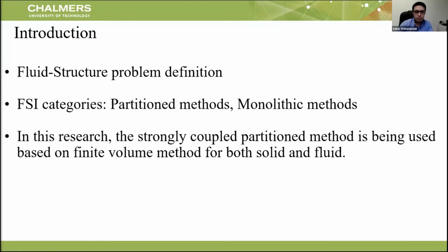In partition methods, the solid and fluid domains are solved separately by using one's favorite numerical method and possibly non-matching computational grids. Partition methods can be divided into strongly coupled schemes, which enforce the discrete counterpart of both coupling conditions up to a tolerance of choice, and weakly or loosely coupled, for which the coupling conditions are not exactly satisfied at each time step.